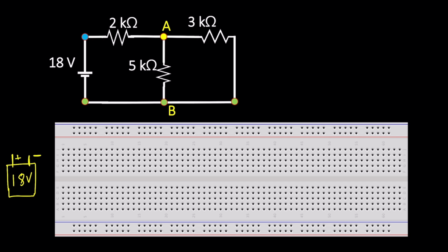First, whenever you get a breadboard, you need to connect these two terminals such that you can use the full power rail. Now you already have the voltage source, so connect that voltage source to the power rail. I connect the wire from the positive terminal of the voltage source to power rail 1, and connect the negative terminal of the voltage source to power rail 4.